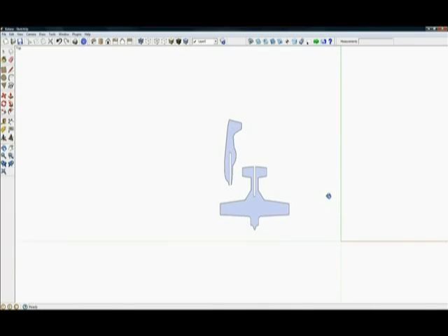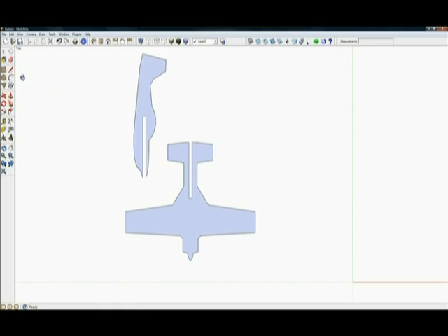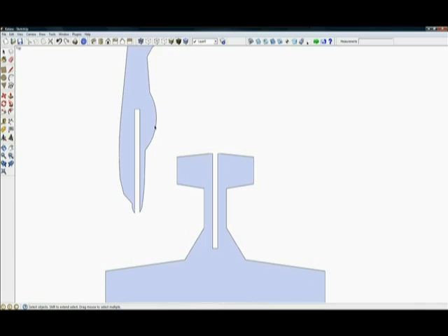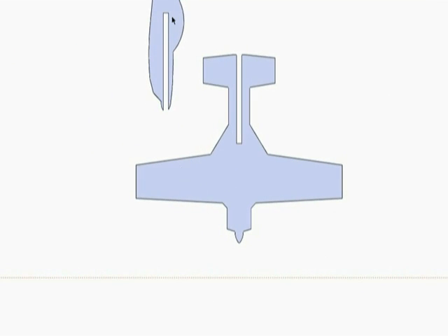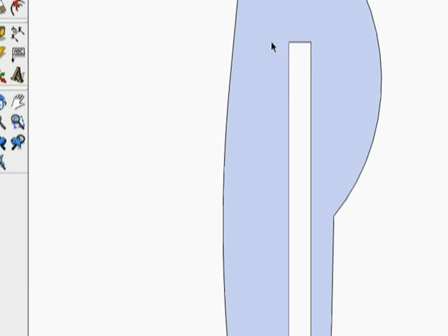And some considerations. Now, I'm not going to show you how to design. I'm showing you how to use SketchUp here. But some things that I did when I was working this: I normally like to work in inches, but I like to work in metric as well because I don't like having to deal with 4 decimal places as much when I'm working up a design. Now, I have determined in the past that fanfold foam, although it's advertised as 1/4-inch, is really closer to 6 millimeter. So that being known, even though I was all in inches, I was able to work up my slots to be 6 millimeters wide.